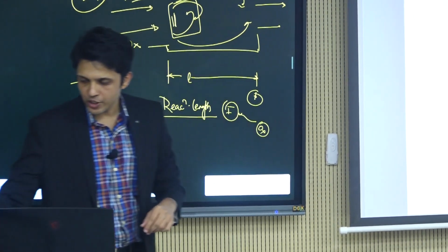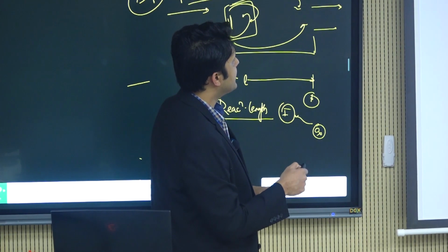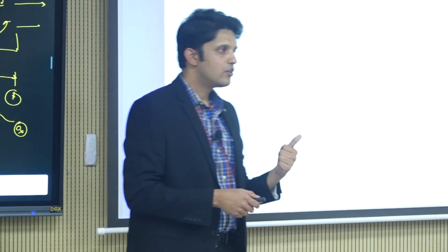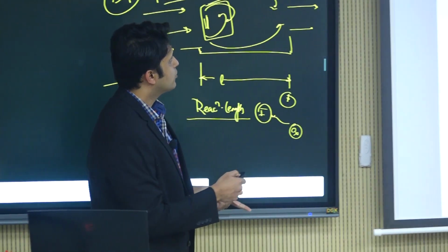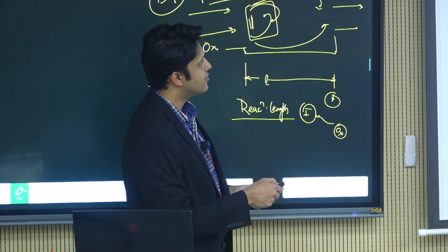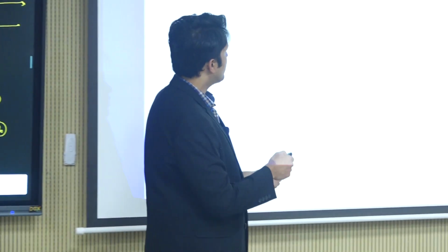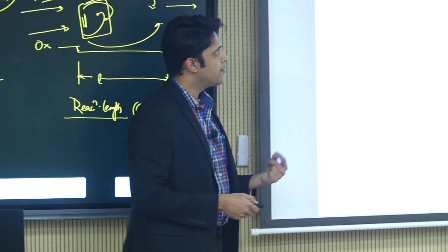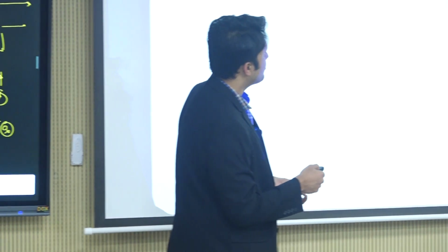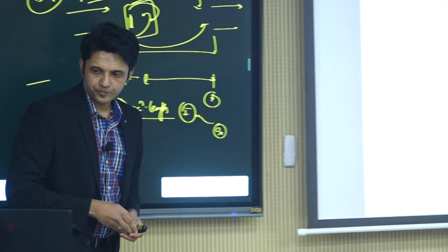The assumption to calculate this is that you have a steady flow reactor, with reactants entering at standard reference conditions. What is the standard reference condition? Temperature is 298.15 K and pressure is 1 atmosphere, right? They enter at that condition and react within this vessel. They completely react to produce C plus D as products, and the products exit at standard reference conditions, right? So the products' temperature is also 298.15 K and pressure is 1 atmosphere. This is a stoichiometric mixture, so all the reactants are completely burnt, and the reactants and products enter and exit at standard state conditions.